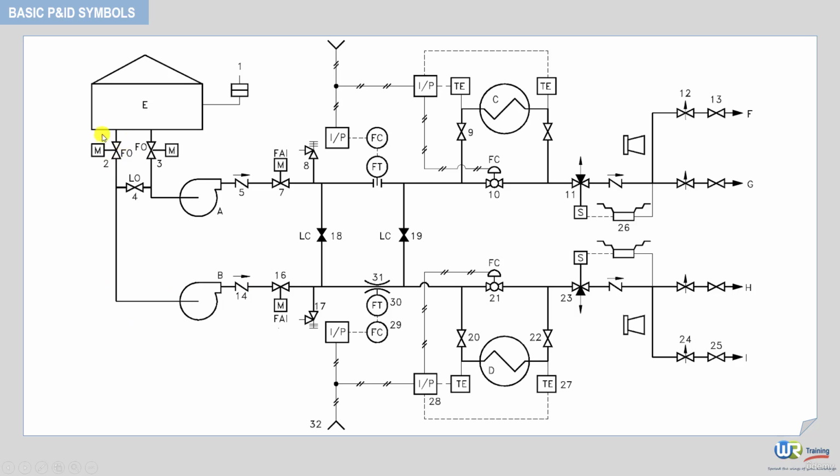You can see here an electrically actuated valve, a pump, a check valve, a second electrically actuated valve, a pressure safety valve, a Venturi flow transmitter with a flow controller, a control valve, a solenoid three-way valve, and a check valve. At this level, the pipe is split. On both branches, you can see a needle valve and a gate valve. From the symbology, the arrows that you can see here, and the configuration of the different check valves, we understand that the flow path is from left to right.